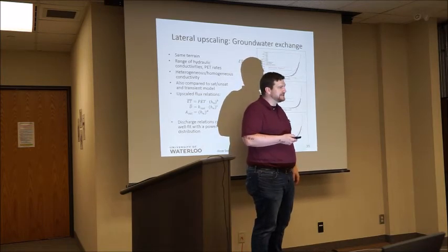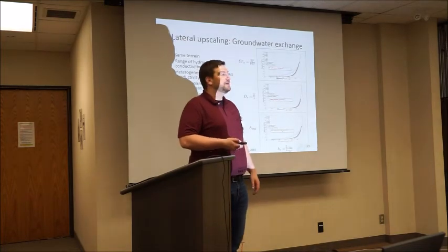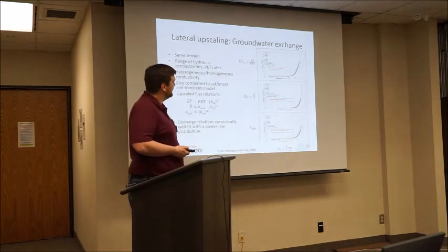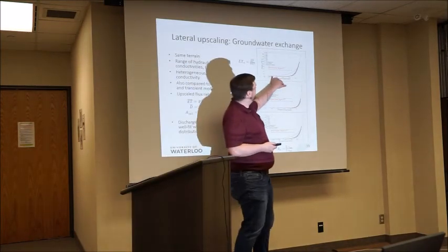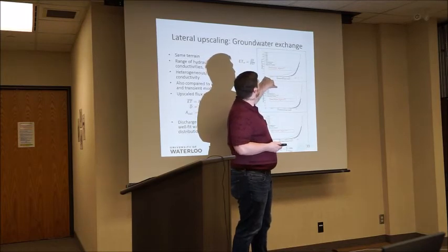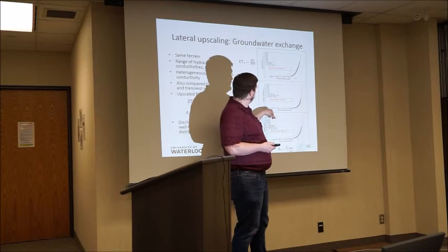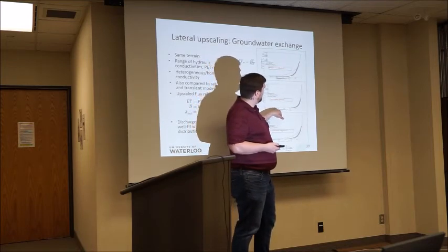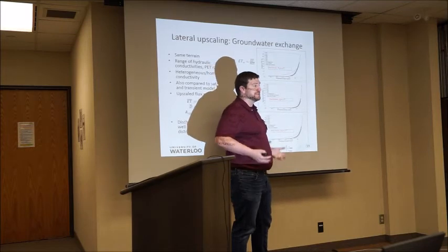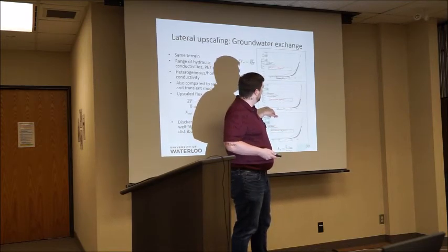Again, one of these curious things: why are these conceptual models working so well? They're accidentally upscaling physical processes that they're inferring from looking at the hydrograph. And this is what we would get if we just naively upscaled the point scale process. This would be our ET trend. It's not right. Likewise here with discharge, there is no naive upscaling of discharge because the discharge doesn't present itself until the water emerges from the ground surface.